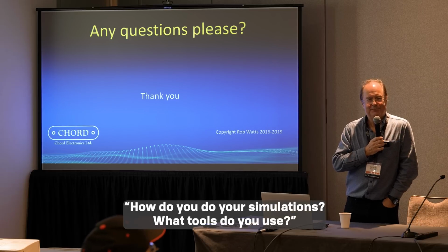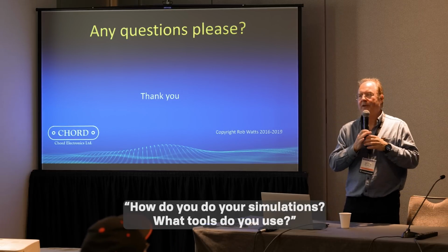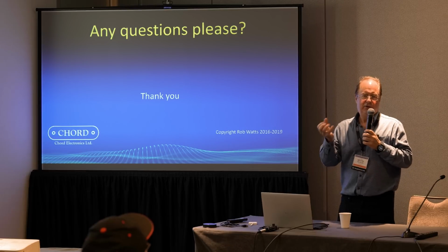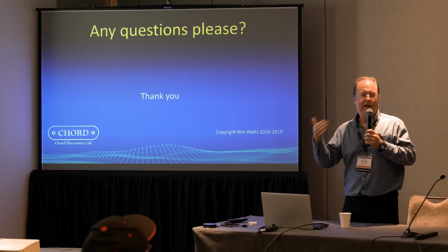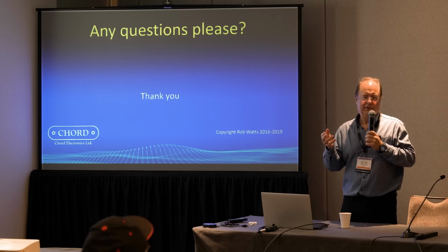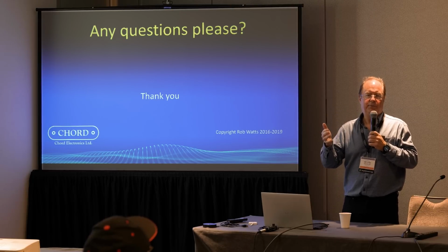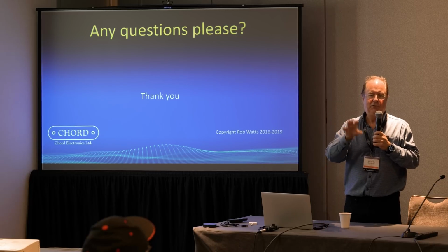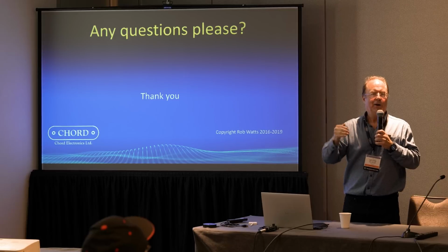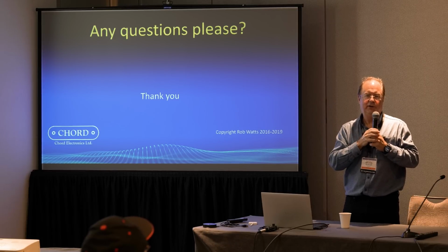I would like to know how you do your simulations, what tools you use. Okay, so it depends what you're simulating. If it's a digital circuit, you'll use Verilog. The Xilinx tools have got a Verilog simulator built into it. So you do a behavioral simulation, and so long as the place and route is done correctly, the output from that will be identical to the hardware implementation that you actually do.